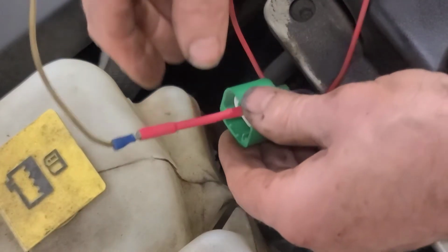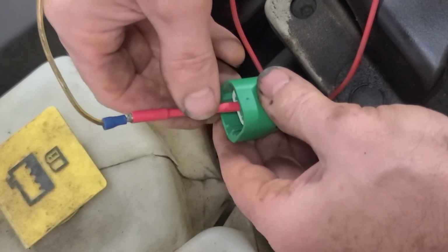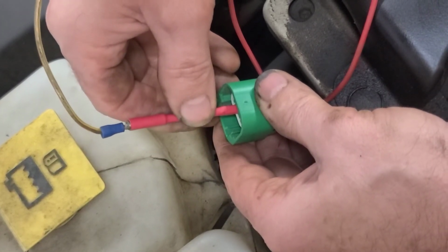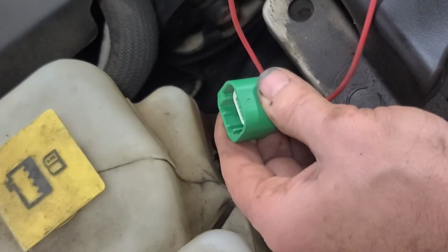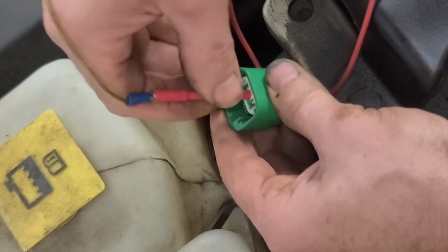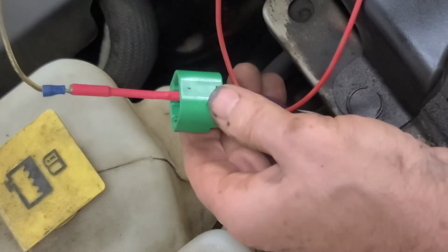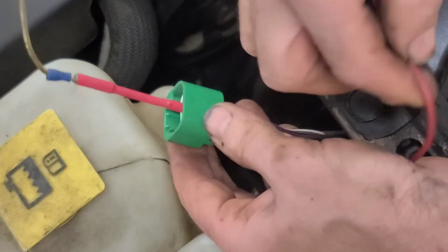So the black and pink wire is the middle wire here, and I've got a headlight connected to the positive battery post, so if I find a ground, the headlight will come on. It should come on when I attach it to this terminal, and it doesn't. So I'm looking for a possible break in this ground wire.